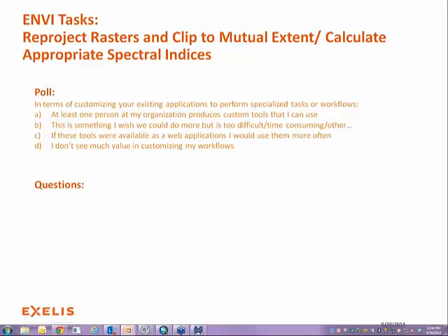Great. The next question is, what is a good source of LiDAR to produce 1 meter or any other high-resolution surface like you used in the demo? Okay, so I mentioned NSF OpenTopo, and that's a really good website for existing LiDAR. A lot of times the point cloud density is pretty low for those data sets, but using something like ENVI LiDAR to process to a 1 meter DEM or surface model, DSM, that's really sufficient.